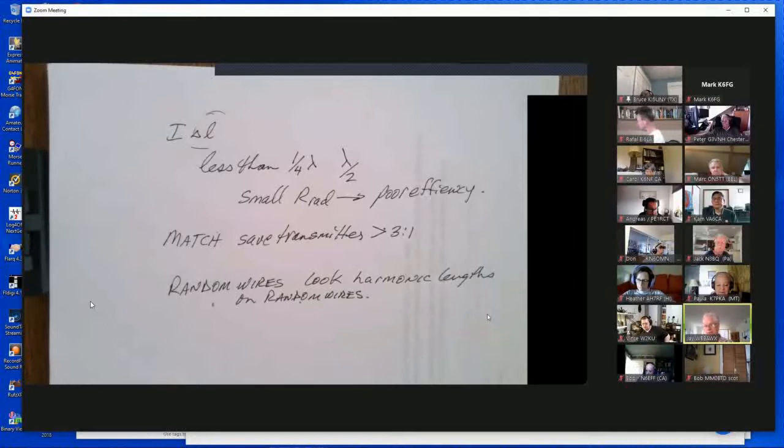But if you're laying that out in your backyard, or you have a very short antenna, you're going to want a lot of radials. I have a tower out back, which I use for 160. I have 16 radials on it, and I find that works very well. It's a fairly good sized tower, so it's not a full quarter wave, but it's close.